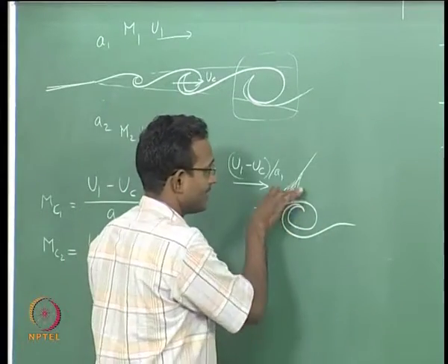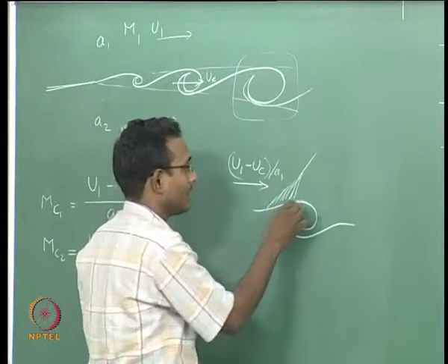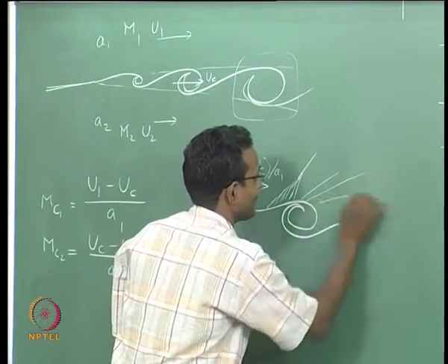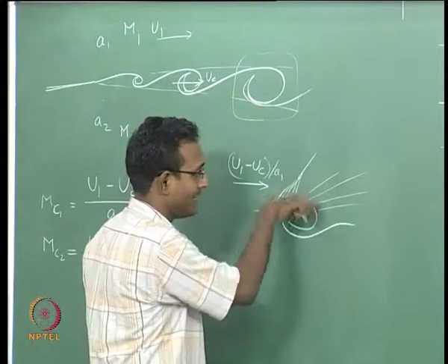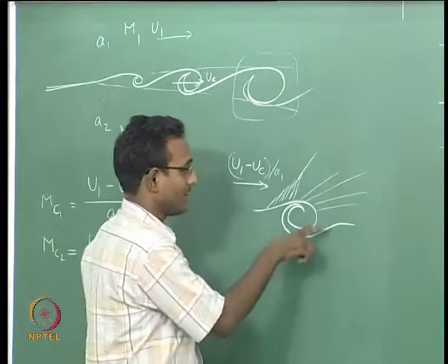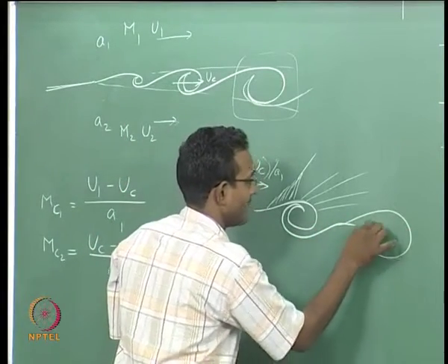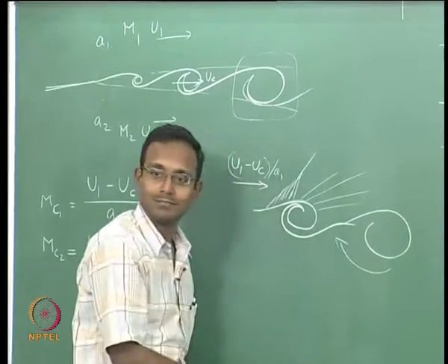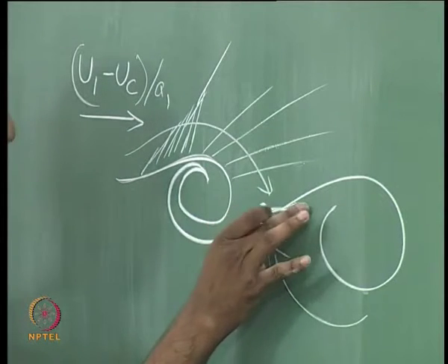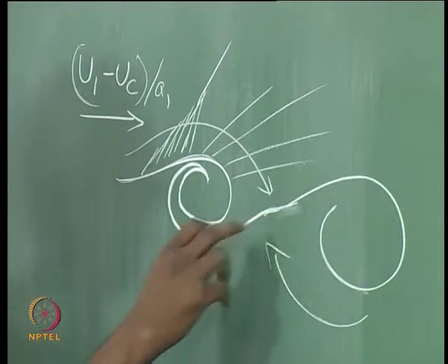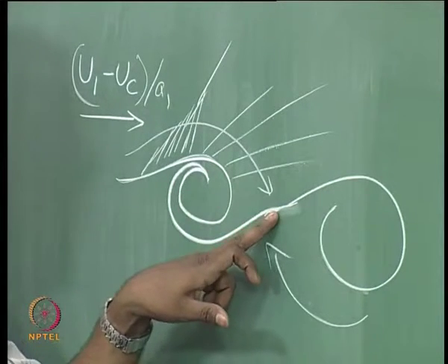After that, it is seeing this turning, right, that is the induced velocity because of this vortex rotation also. So they will suddenly start seeing expansion fronts here, and immediately after that it is seeing a point where it cannot go anymore, this line. Why can't it go anymore? The next guy is sending fluid this way in, while this guy is sending fluid out this way. They are going to find an intermediate locally, something like a stagnation point there. It is not really a stagnation point, but with respect to these two structures it is like a stagnation point.